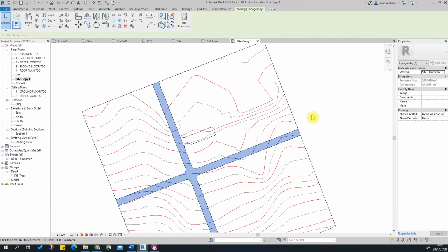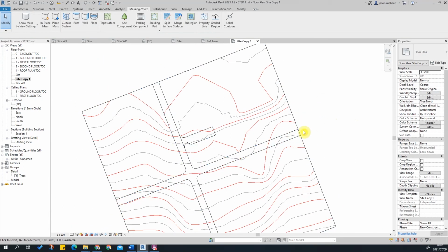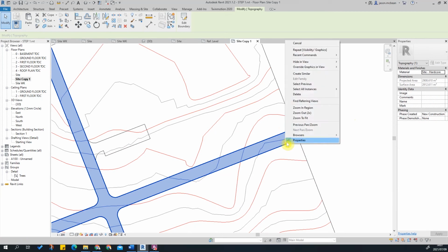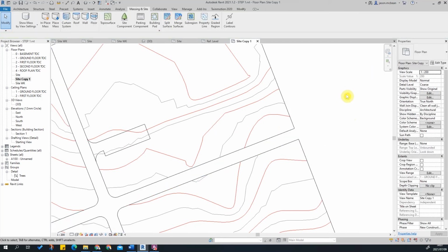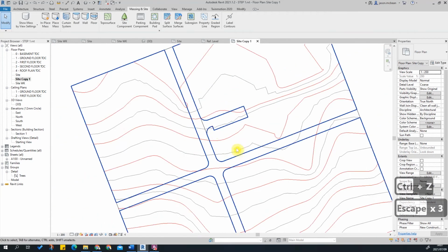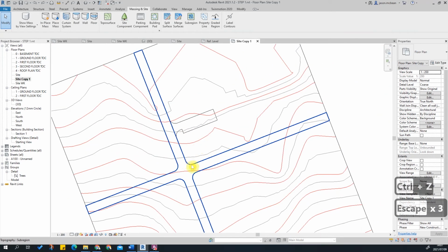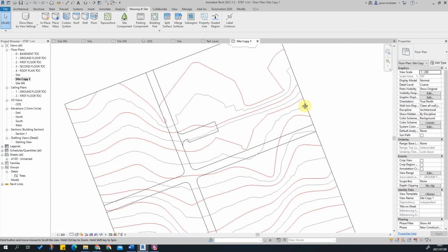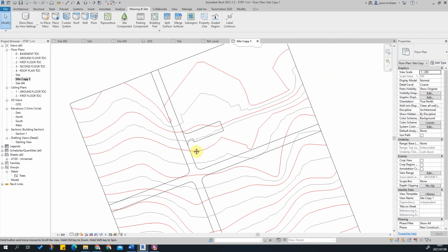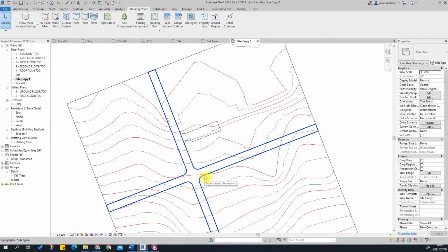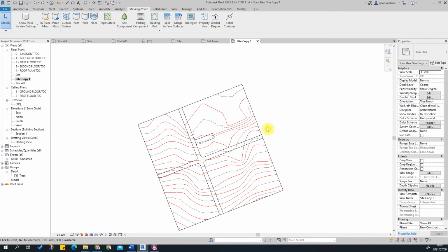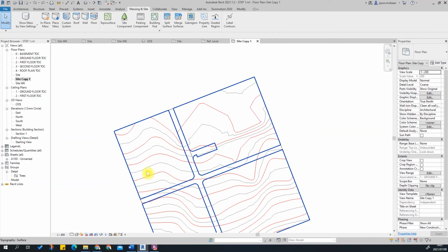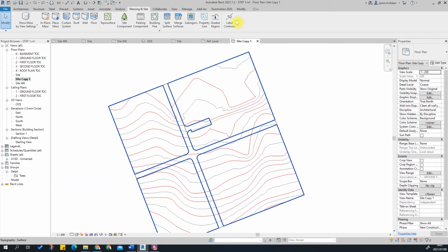Okay, so in AutoCAD, you've actually got to go and switch off these subregions. Let me just see if it'll hide in view elements. No, see, it deletes the, so it's part of the site information. Okay, now, unfortunately, there's no other way to do this. So what I typically do is I export this as a DWG file now, and I reload it in, and then explode it and get rid of the information I don't need. Okay, so I steal the contour information, maybe add some labels.